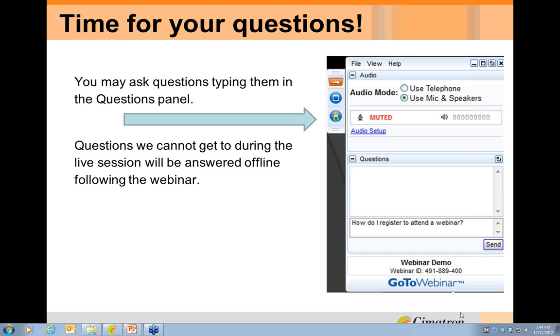Another question is kind of similar to that. Will the assemblies get too large if all of the revision parts are kept inside it along with the mold design? Yeah, that was actually one of my first concerns too about this. It's possible. We've got some customers that do very, very big mold designs, automotive parts, huge stuff. And yeah, we're keeping the part revisions in the main assembly, but they don't have to stay there. After implementation, after we've done our check, you can suppress those. I don't think it's going to be a problem. By suppressing the parts afterwards, you can really keep the assembly size at a minimum.